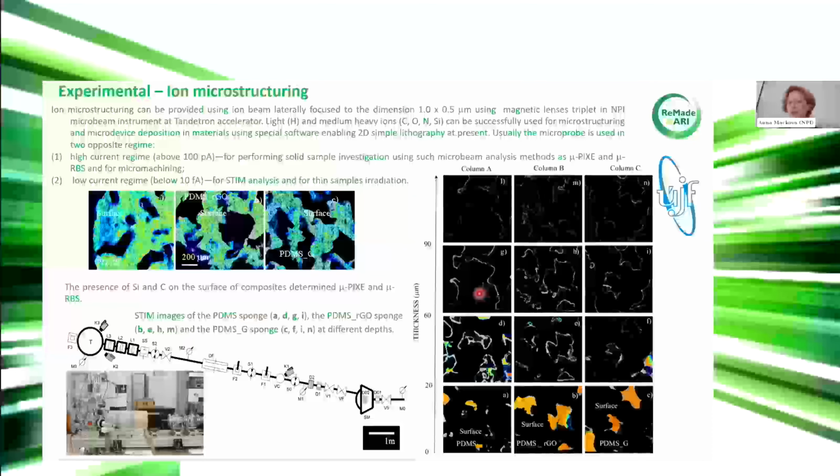So with increasing fluence, we saw that the internal stress and radiation damage are not so critical if we are using a combination of gold and silver, because silver is lighter and does not deteriorate the structure of the nanopillars so much. And here we can see then how they look.